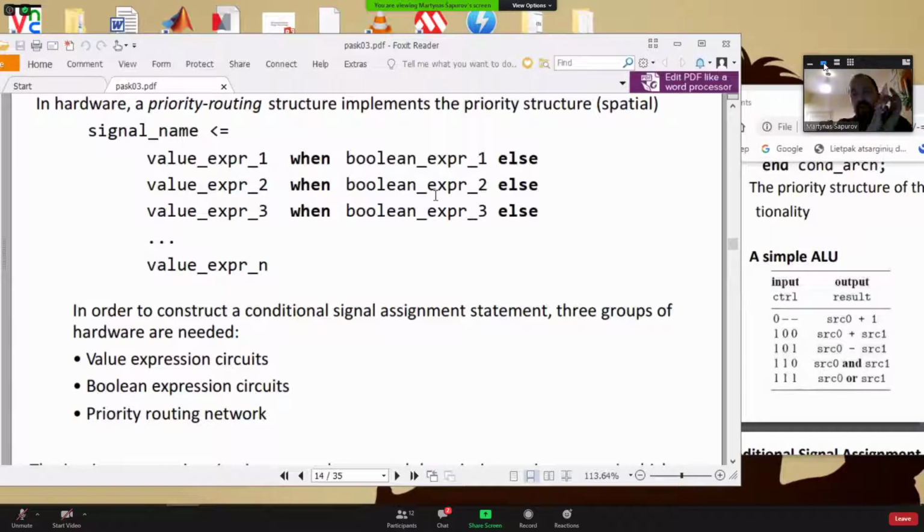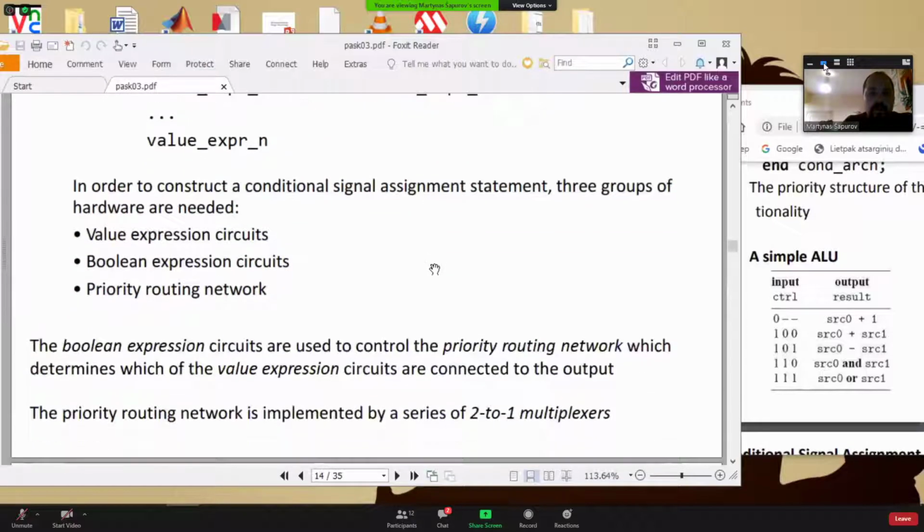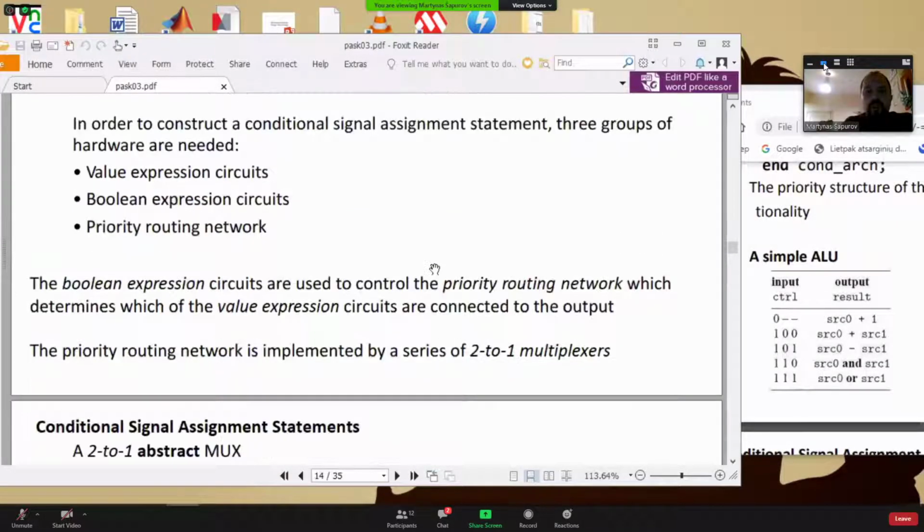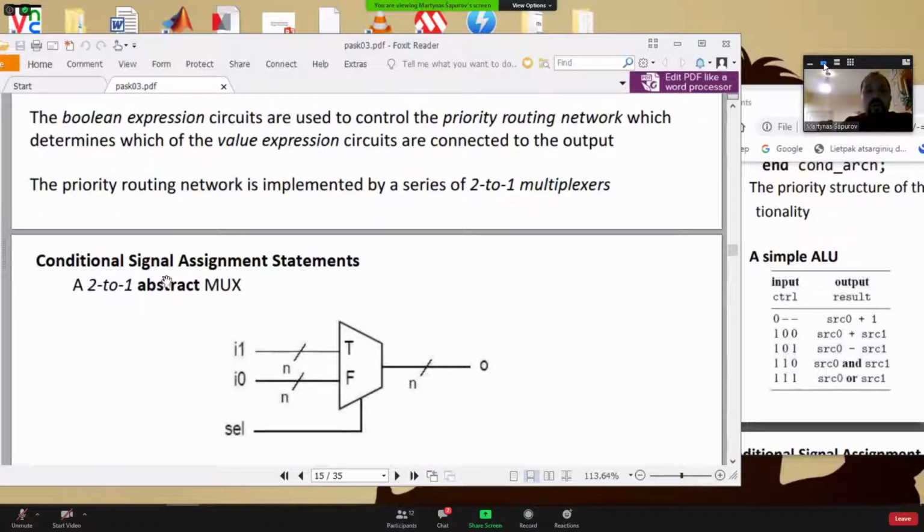So this means, as it's a combinational part and it's executed at the same time, we are not able to split the operators in time, and the only part we can specify is how to arrange the circuit in series. And now we'll see how your real circuit looks. So we could express each condition checking statement as a multiplexer 2 to 1.